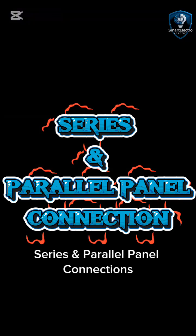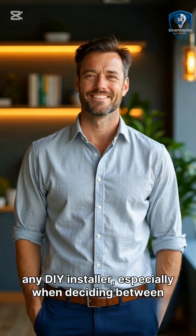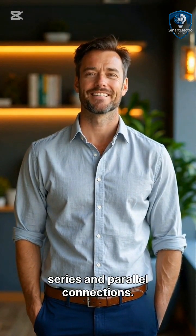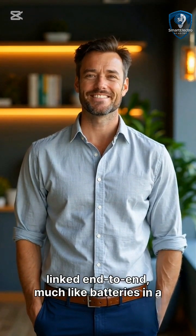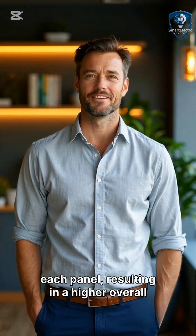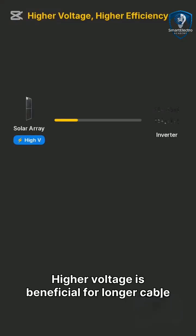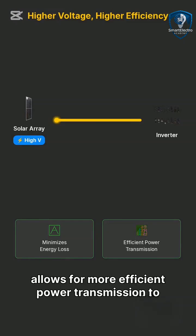Series and parallel panel connections. Understanding solar panel wiring is crucial for any DIY installer, especially when deciding between series and parallel connections. In a series connection, solar panels are linked end to end, much like batteries in a flashlight. This configuration adds up the voltage of each panel, resulting in a higher overall system voltage. Higher voltage is beneficial for longer cable runs, as it minimizes energy loss and allows for more efficient power transmission to your inverter.